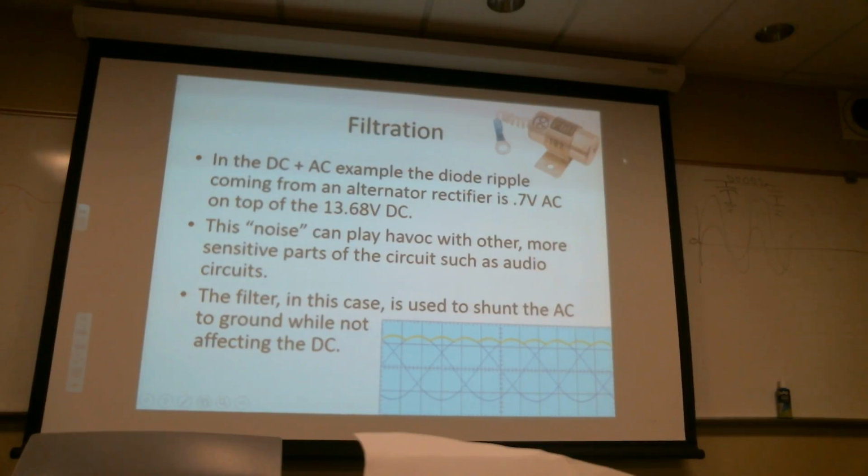Well, the truth is there's some frequency where it's perfect. My guess is what I would do is say, the average airplane engine flies along at 2,200 RPM or 2,400 RPM, whatever that value is. The alternator is spinning 6 times that, so whatever that frequency is, times the number of phases in the winding, come up with that frequency value, tune to that, but make it as broad a pass filter as possible so that it filters all the way down and all the way up to a range reasonably well. But down at idle or maybe above the top high RPM, it doesn't work quite as well.